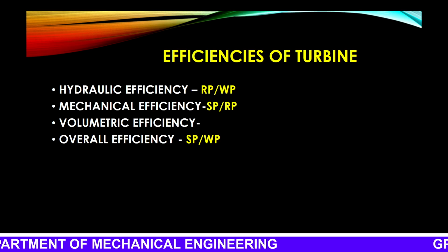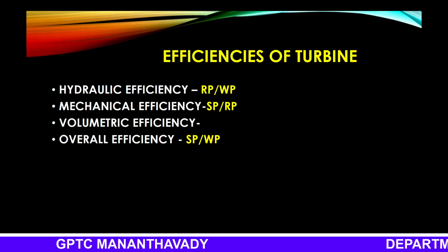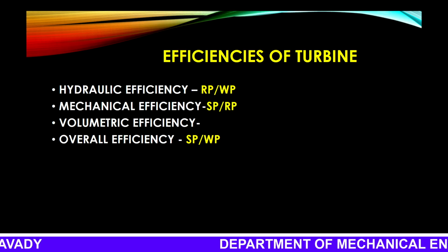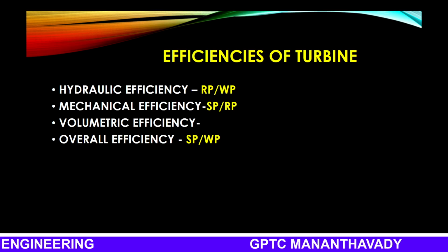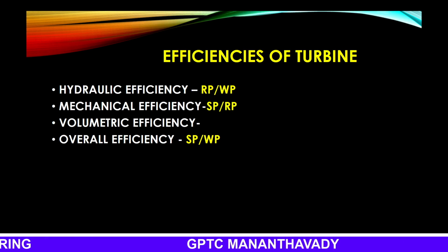Normally the power at the inlet of the turbine is more. And this power goes on decreasing as the water flows over the vanes of the turbine, due to hydraulic losses at the vanes, and the vanes may not be smooth. In previous sections, we discussed that during derivation the vanes are assumed to be smooth. But in actual practice, the vanes are not smooth.